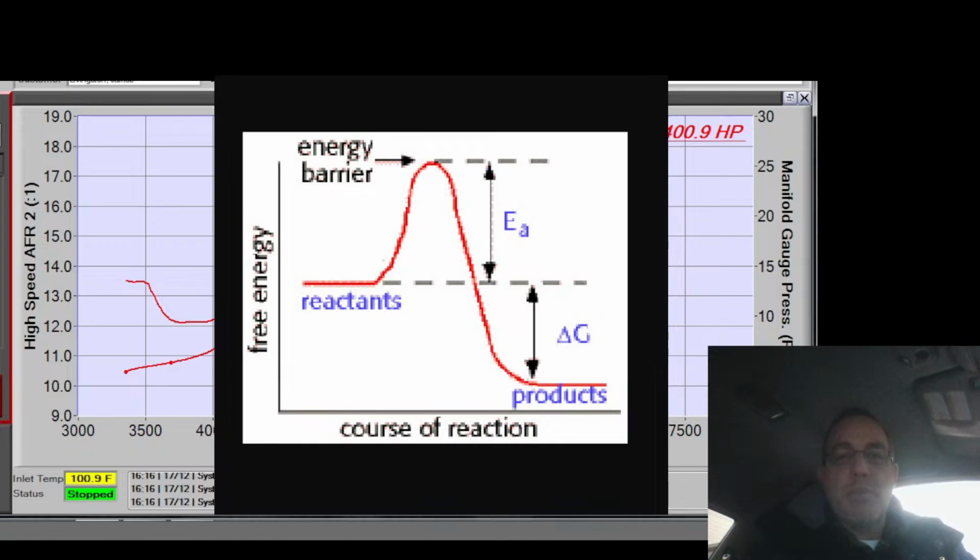So it may not be squeezed out. The pressure could be just a little bit, really. Honestly, the pressure is probably pretty low, because it takes more energy from the spark than from the pressure to make it blow up. But the point is that pressure gives us a portion of the energy needed for this reaction to happen. And in subsequent reactions, the pressure in the cylinder also gives us energy towards further reactions. And what's important about this is that the proximity of the molecules to each other has another huge effect on burn speed, which I talked about earlier. And this is where I wanted to go with burn speed.